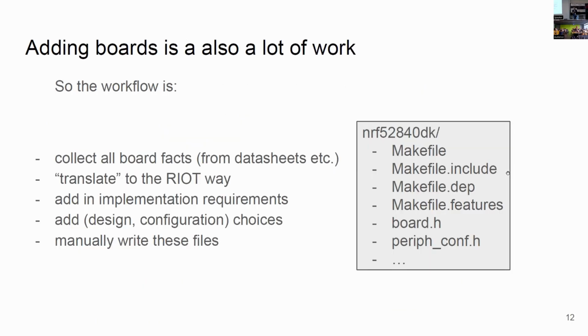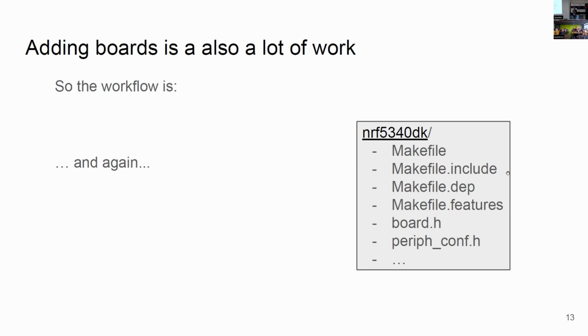So the workflow: these facts need to be collected somehow from datasheets. Then you need to know how to express them in RIOT, how to put them in the headers. Then you need to add in the requirements by the implementation. And then the design choices of RIOT need to be known. And that has all to be put into the RIOT files for a board. And by the way, of course, again for the next board, and for the next board.